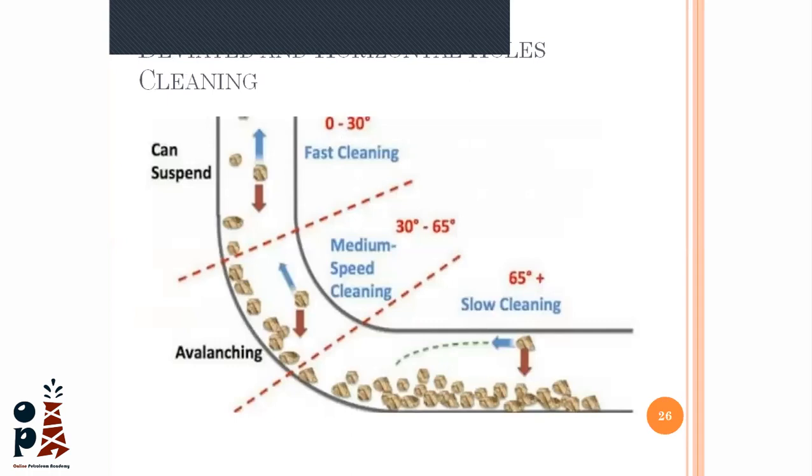Okay, guys, here we are going to talk about the deviated section. In this schematic, we have three parts of the well. When we drill vertical, as I told you, it will not be a big deal. We will maintain our annular velocity. We will maintain our viscosity. We will overcome the slip velocity, and it will be okay. So hole cleaning will not be an issue.